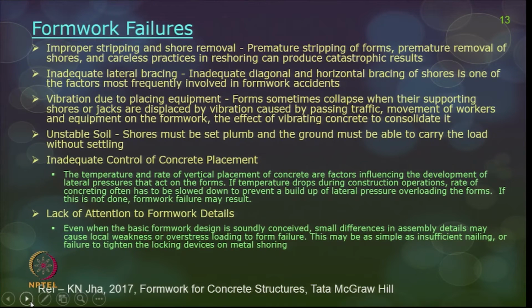In spite of this, there can be so many reasons for formwork failures. Improper stripping and shore removal. Okay, what happens is, initially when a house or a building construction happens, first they do the wall and column formworks after the foundation, and then they do the slab or the beam formwork, putting all the props and supports. After the concrete has attained sufficient strength, these props may be removed and the shoring generally happens, and then the forms are replaced or put into the floor above. Okay. And this shoring and reshoring keeps on happening until the concrete has attained sufficient strength and so on.